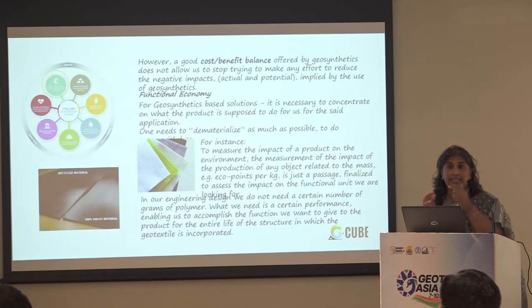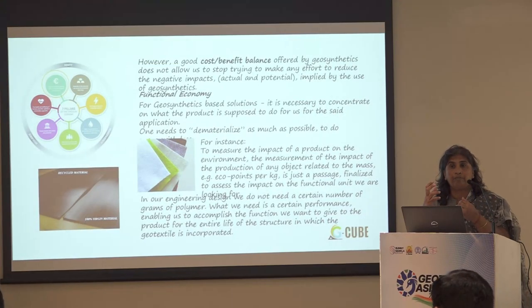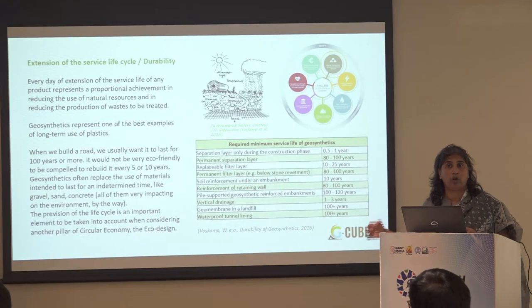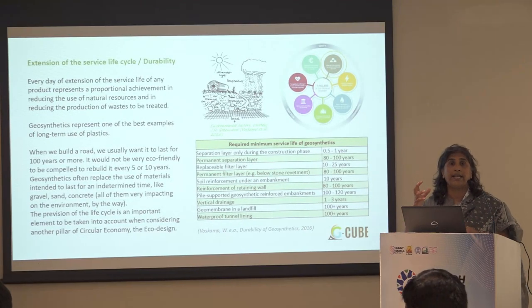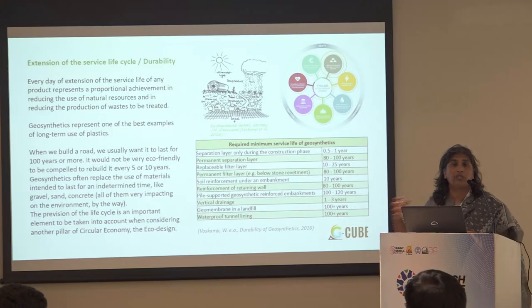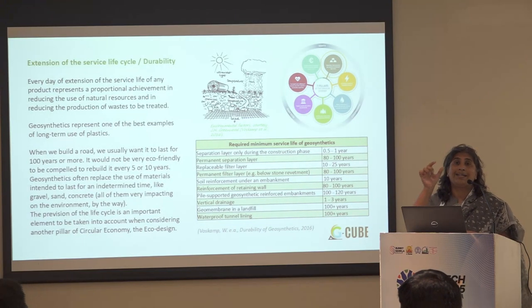especially in terms of recycling. For instance, if I'm talking about a non-woven geotextile, one of the simplest basic products, and I'm talking about, say, a product for a particular application like separation, typically the language that is very often used is "use a 500 GSM textile." Now, this can be one of the worst specifications possible. The reason being, grammage cannot decide the specification of the product. It is the polymer, it is the function, and it is the properties of the product.